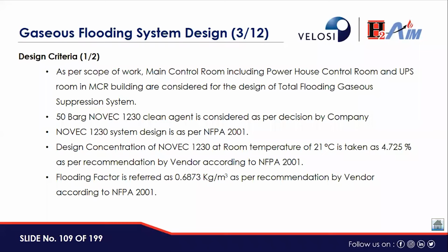What are the design criteria we have selected for the flooding system design? As per the scope of work, the main control room, including the powerhouse control room and UPS room in the MCR building, are considered for the design of the total flooding gaseous suppression system. 50 bar gauge Novec 1230 clean agent is considered as per decision by the company.